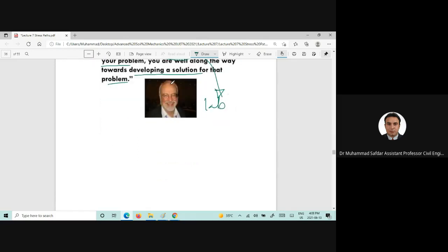and then you test that in the particular condition which will occur in the field, and you find out the shear strength parameters and put them into your numerical model.